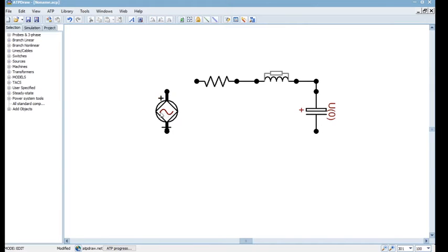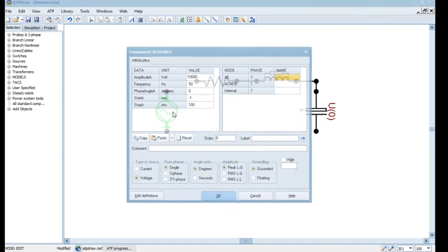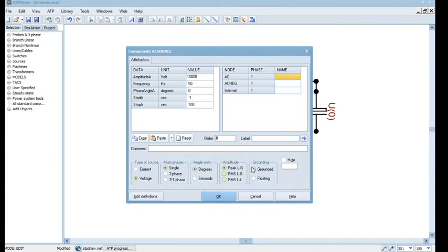Okay, yeah. When you place this for the first time, it will give you a weird picture, but once you open it, it will prompt you to enter some values. So let's do that. We want a voltage source, a single phase source, angle should be in degrees, and amplitude is line to ground we are specifying. Let me choose that as 10 volts to begin with. Frequency is 50 Hertz, phase is 0. At start time it's -1. So it's a very key thing here.